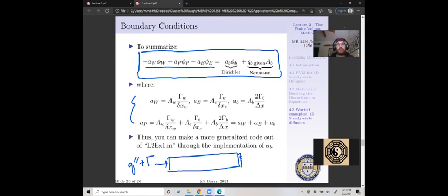We'd have basically three boundary conditions where only two are necessary. So we can't apply both a Dirichlet and a Neumann in the same stencil. Say this is control volume 1. Here is our east, here's our P. We can't specify both temperature and flux on this western face.